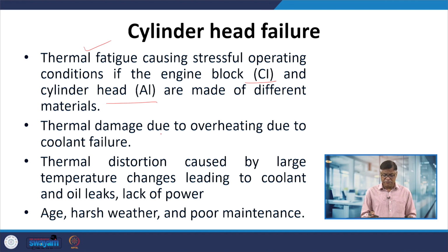Thermal damage in the form of distortion due to overheating can occur in case of coolant failure, and thermal distortion caused by large temperature changes can lead to coolant or oil leaks and a lack of power being generated by the engine. Similarly, aging, harsh weather conditions and poor maintenance can also cause damage to the cylinder head.